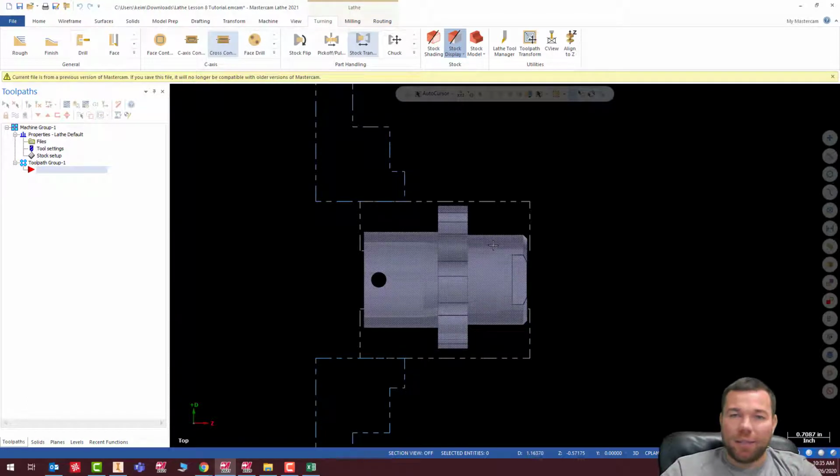I only pick the DZ plane usually because it helps with creating geometry. I can just type in diameters instead of radii to create my turn profile. But since I already have it as a solid, it doesn't really matter which plane I work in. I just work in DZ out of habit.